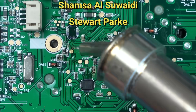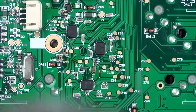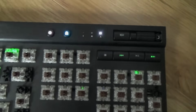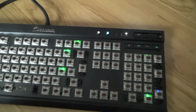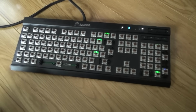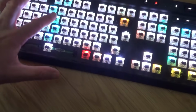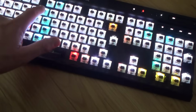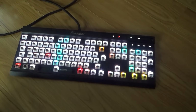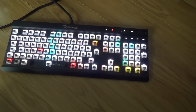So basically we've swapped these chips over now. Let's bring it back to the PC and see if the lights light up in the same order or not. Worried because this light was flashing here, but I just googled it. It's a scroll lock. It means it's in BIOS mode. So if I put it back to here, watch this, it will all come back to life again. But can you see we're on the white background and we still have this row here not behaving itself. You can clearly see now without the keys on, this should be white everywhere. So something is definitely not right.